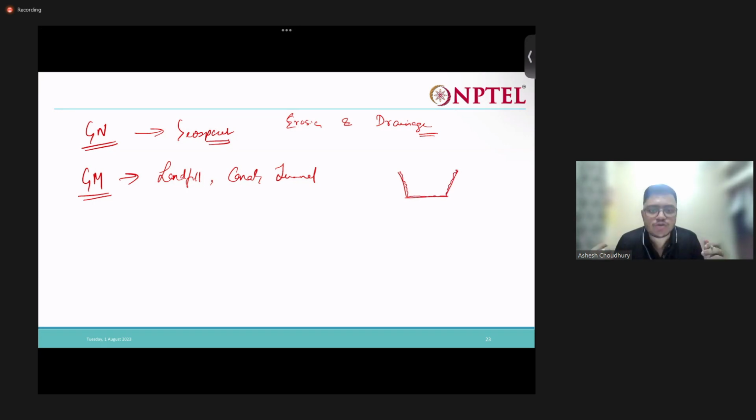With the use of geomembrane, we don't have to make the canal lining with concrete, first thing. And the second thing is that the construction process can be accelerated. Directly above the excavated soil, we can put the geomembrane. This will prevent the water from damaging the soil layer and also from leaching into the ground. Just as if you have a ground and you put a polythene or something plastic over it, it will trap the water inside, right? The same thing. That's all.